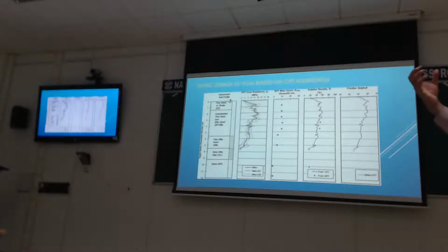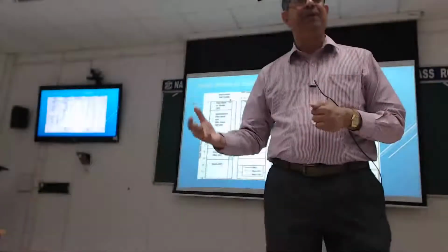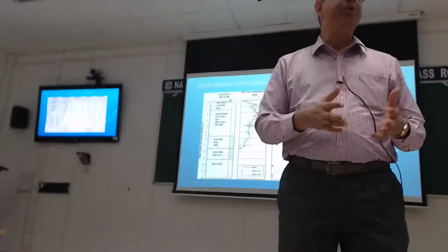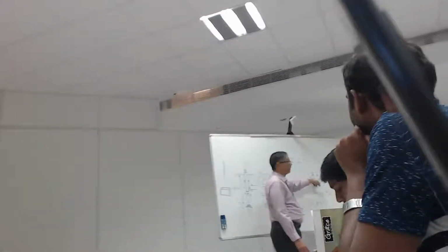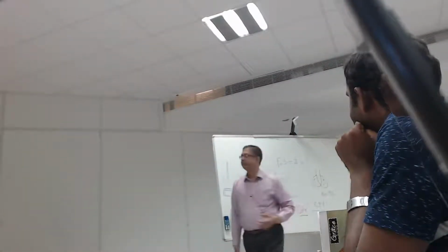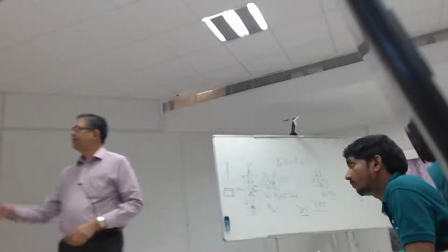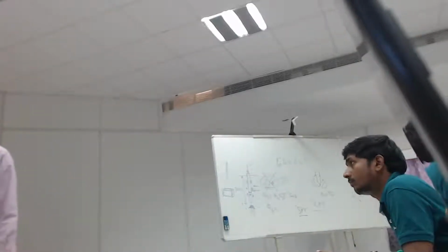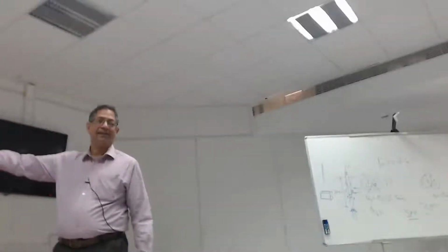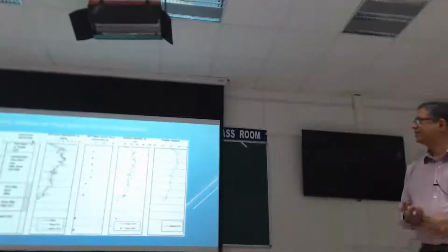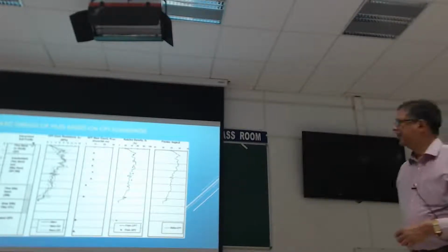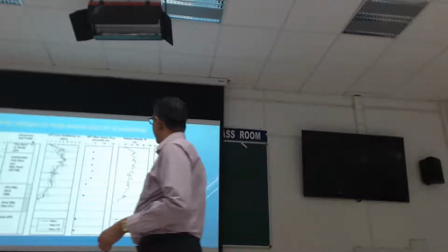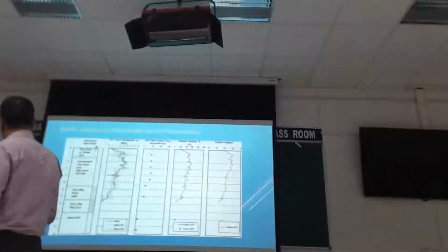And this is why I push for CPT rather than SPT, because CPT should mimic the same flow mechanism as you're driving the pile. You will get the same thing as this, for which we have solutions. And I got this off the website from somewhere. Typically, this is what you will get. You've got your cone resistance, usually in the order of megapascals, cone tip resistance.